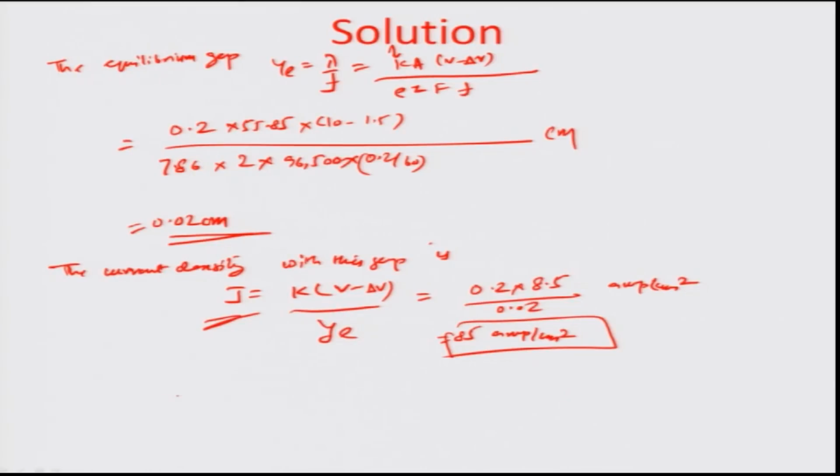The allowable rise in temperature, delta theta, is around 60 degrees, because we are operating at about 35 degrees, and we can at the most go up to 95 degrees Celsius, which is the boiling point of the electrolyte.